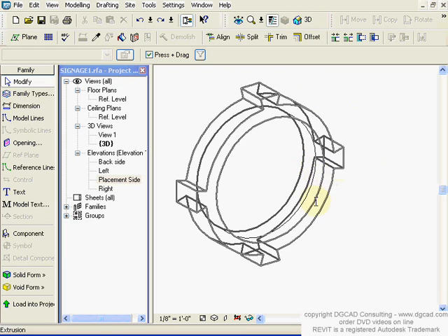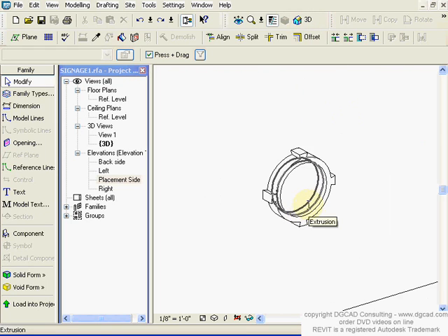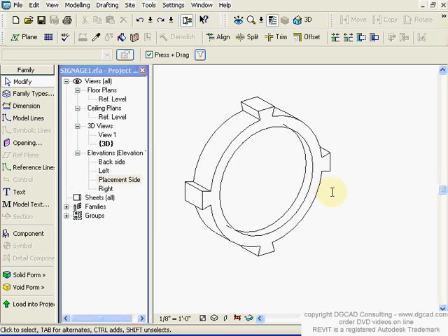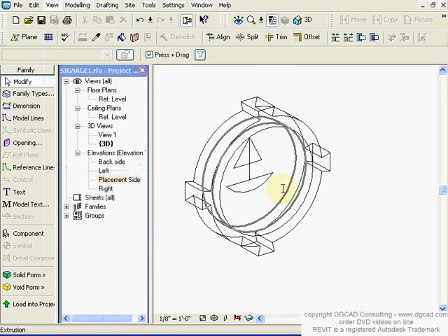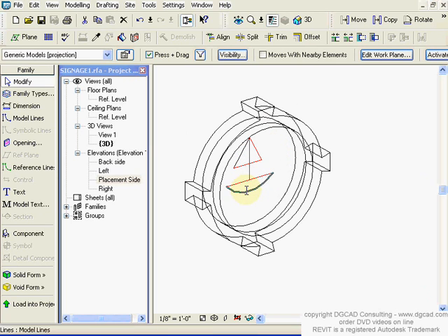I'm going to go back, have a look at my 3D view, and my text is not showing up. Okay, and I've seen this. That's why I kind of checked on that. So what I'm going to do here is I'm going to go click on here, and I'm going to go into 3D wireframe for a second. And I'm going to grab, now you see that? Oh, I see. That's on the wrong surface. I can tell by looking at it. I'm going to grab all those objects. I'm going to grab these objects using my control button.